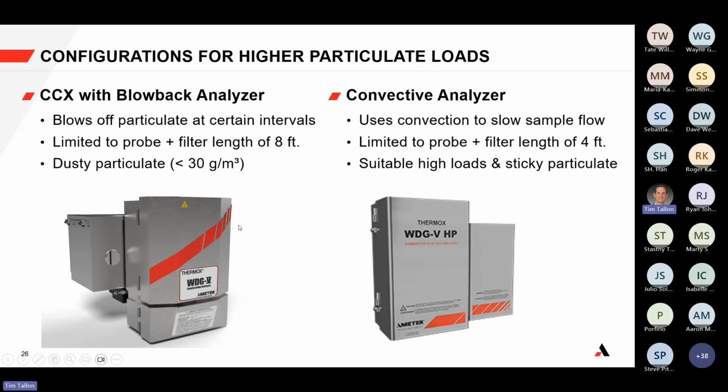Now, when we talk about blowback, that means that there is a puff or a blowback of high pressure air to blow off particulate on the filter in the probe. I'll show you some examples in just a moment, but that's the purpose of a blowback analyzer, is to provide a first defense to puff off and blow off any type of accumulation on the probe and filter.